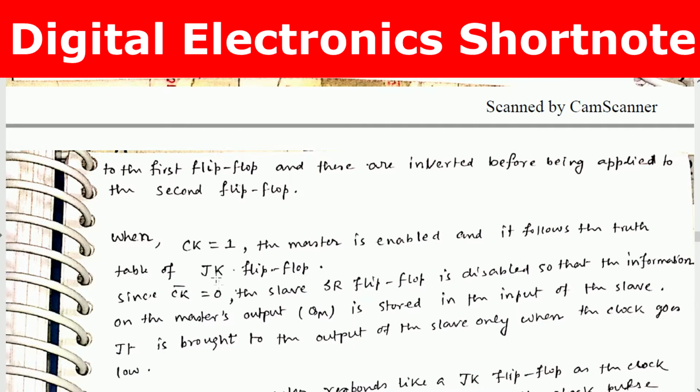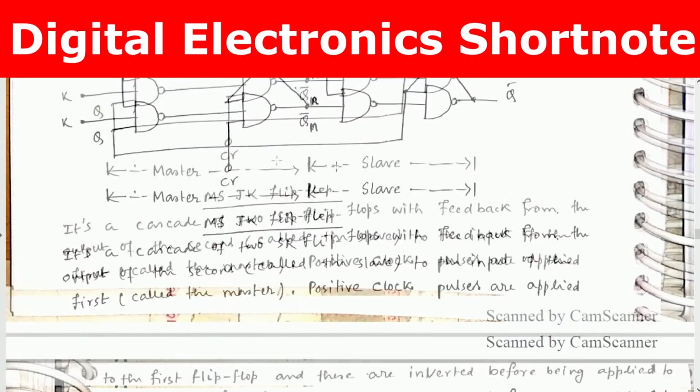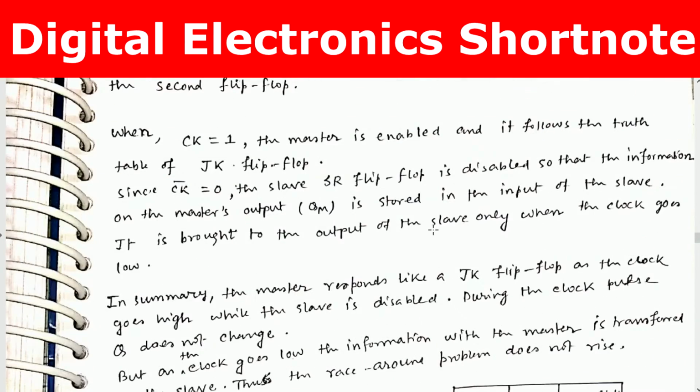Since CK equals 1, the master is enabled, and it follows the truth table of the JK flip-flop. When the complemented clock is 0, the slave SR flip-flop is disabled, so the information on the master's output is stored in the input of the slave. It is brought to the output of the slave only when the clock goes low.